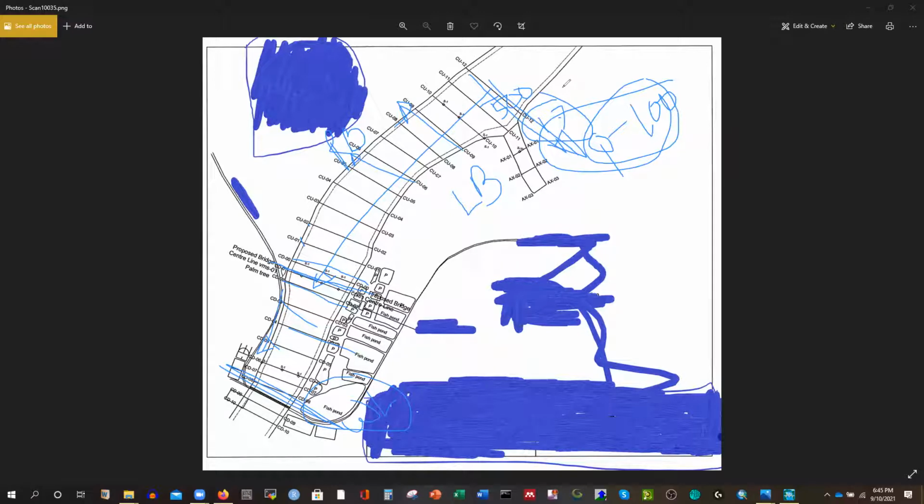Today I'm going to show you how to create the geometry in HEC-RAS. If you have any survey data as an Excel file, we have to be able to create the geometry. I have this data ready, so I'll insert it, and the model I'll run today will be steady state, so there won't be any time series. One value of Q will be fixed for the entire time, and one value of water level will be fixed. Okay, so that's that.